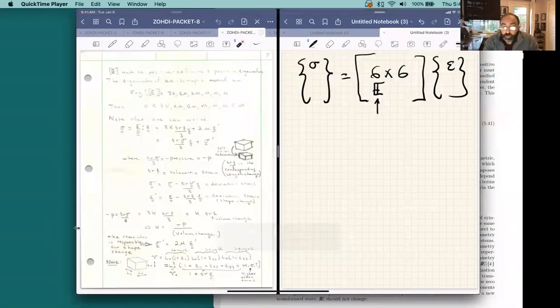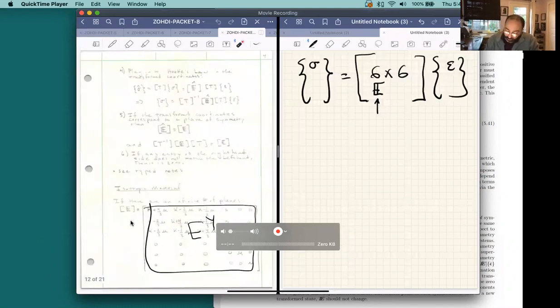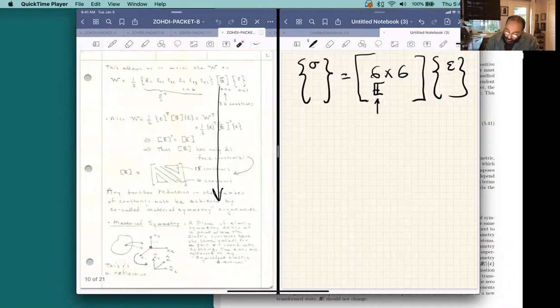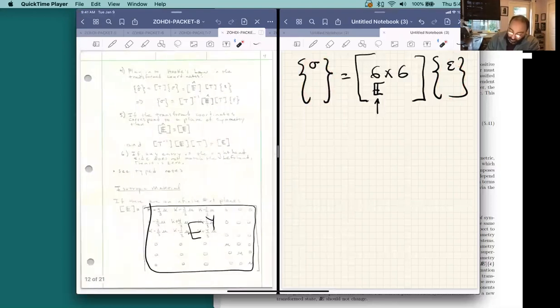So at this point, we start to go through a variety of different arguments, and the arguments basically stem from the following. We essentially assume that, number one, this material has a certain type of elastic symmetry. I mentioned that before. This isn't the subject of this class, but basically it says if the material can deform the same way in this direction, and in this direction, and in this direction, and so forth, we assume that the material is isotropic, and this constitutive law that connects epsilon with sigma can be written in a much more reduced fashion. And that reduced fashion basically looks like the following.